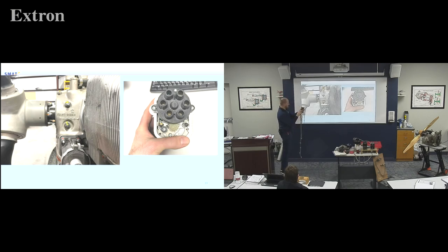Then I go to the next one. Which cylinder is this one going to go to? 3. And then this one. Yeah, so everybody get the idea behind that, of how that works. So we're going to cover that in more detail when we get to the actual distributors, but that's what's going on and why when you look at it and reverse it, it's still the same right or left as there's one gear that you'll see later on when you take them apart.